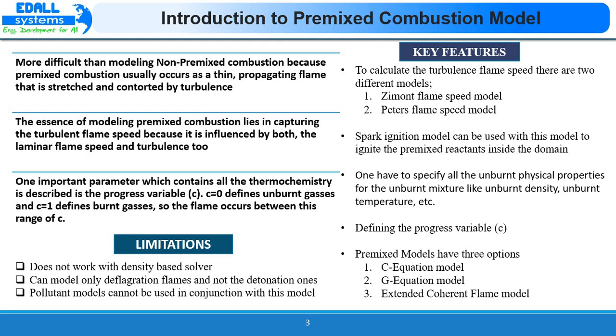Some of the limitations of this model are: it does not work with the density based solver. Also, pollutant models cannot be used with this model, and this model can be used only to model deflagration flames, that is subsonic flames. We cannot model detonation using the premixed combustion model. So this was a complete overview of the premixed combustion model.